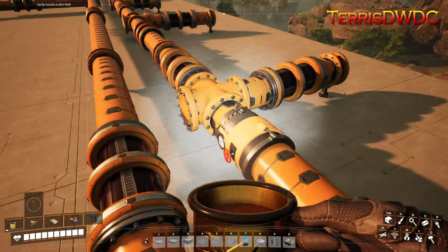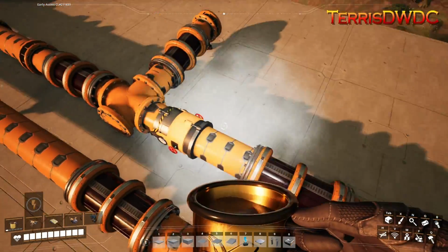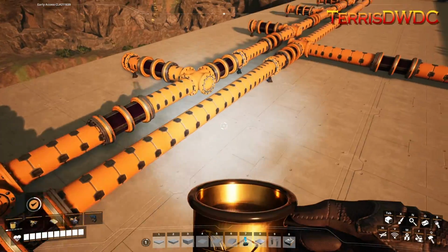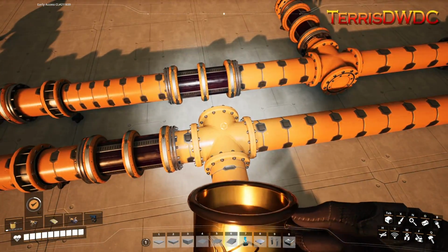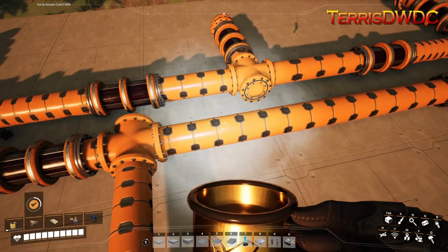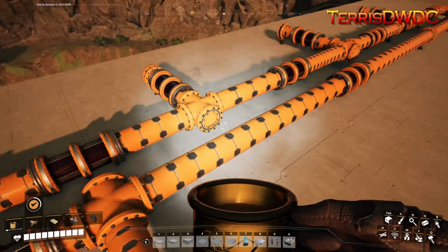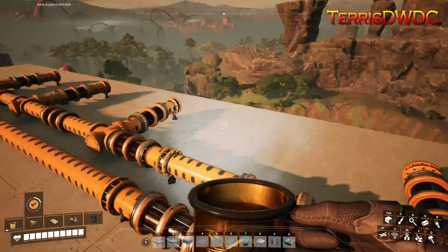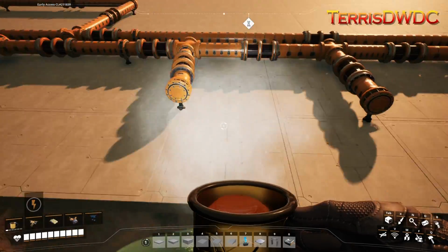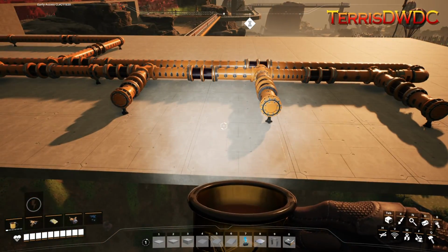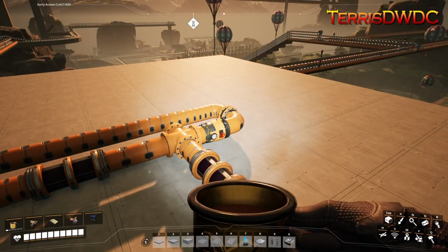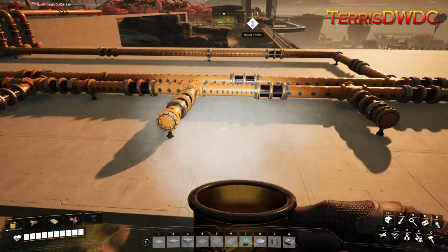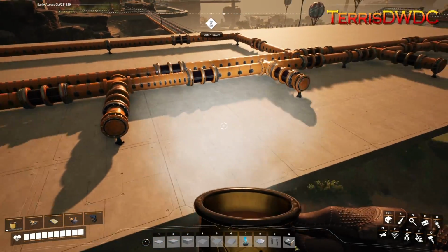So now you've got basically 300 cubic meters of fluid that's going in this way, 300 cubic meters that's coming in this way. It's dividing it nicely. I know it's not really like this pipe, if it's not running, is going to fill up to 600 cubic meters, but now it's pulling fluid from both sides, because these 3 pieces of equipment that are going to be connected at this end, they're pulling from this side first. And then if there's anything else remaining, they'll go to this side. Same with these 3 pieces of equipment that are at this end.